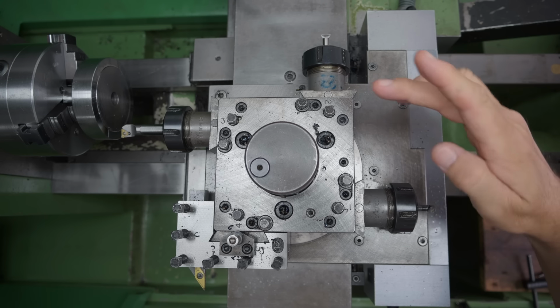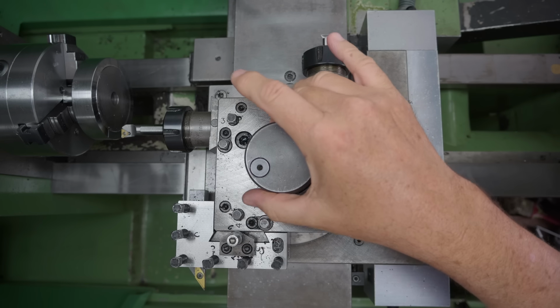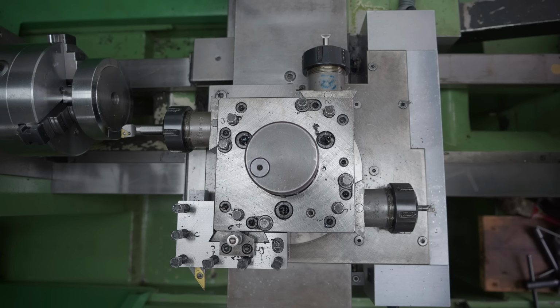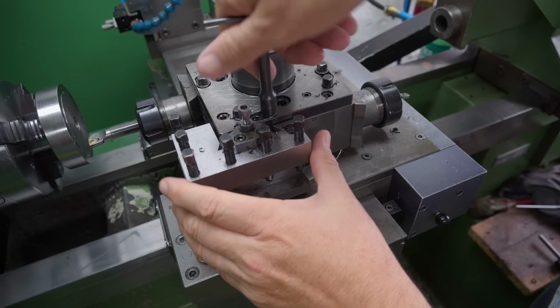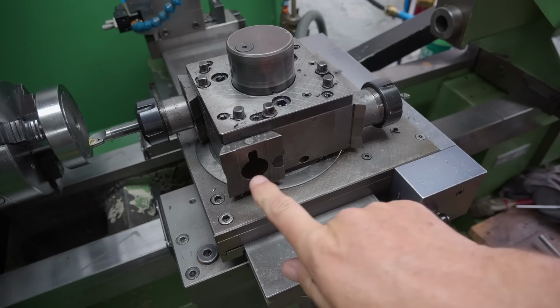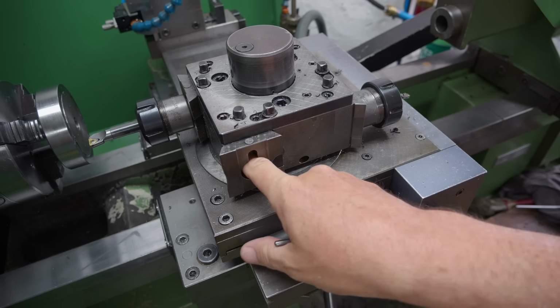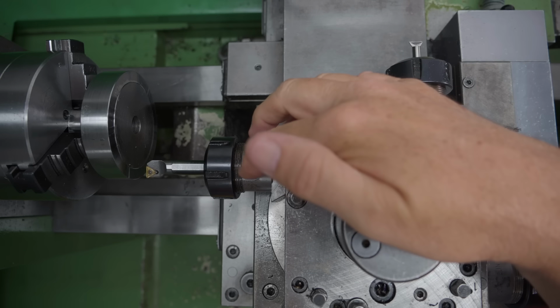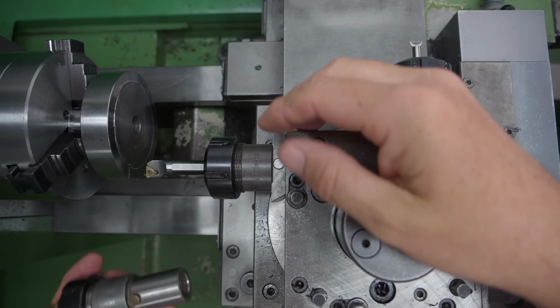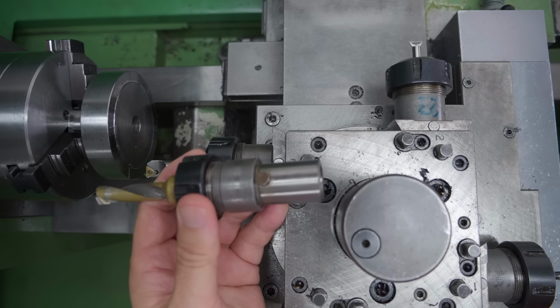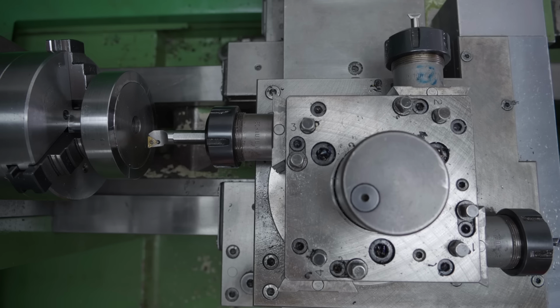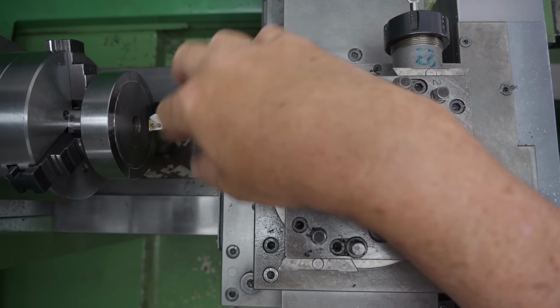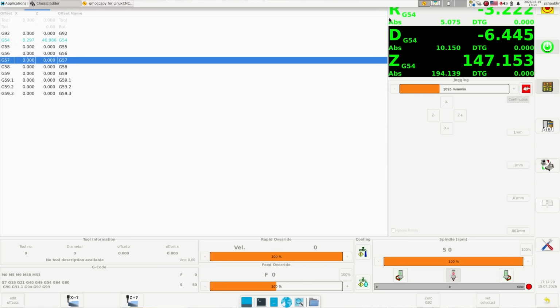And that got me thinking, because this lathe's got this auto tool changer, which has 4 positions, and each of these positions can take a tool cassette, but also boring bars or round tooling in these holes here, which are very precisely located and allow me to position things like round tools, such as drills or taps and stuff like that, repeatedly on exactly the lathe spindle center line. Now, the way the lathe's set up so far, I've got quite an offset between that center line position and a drill set to drill on center.